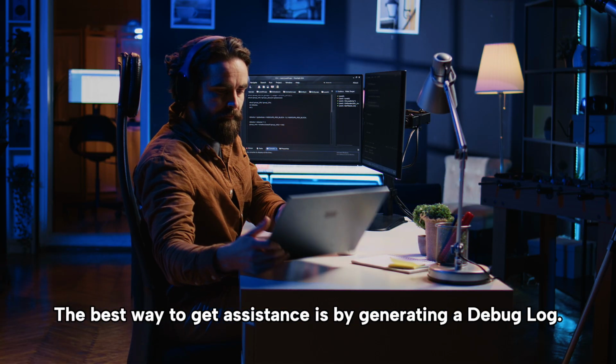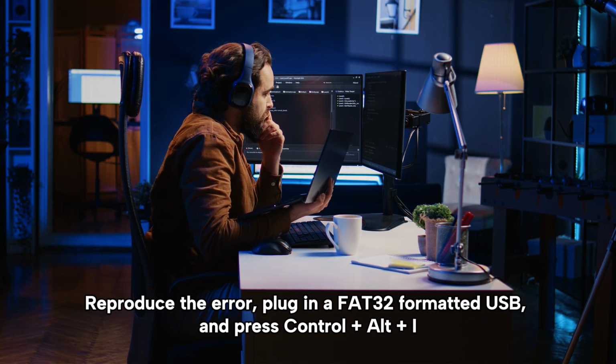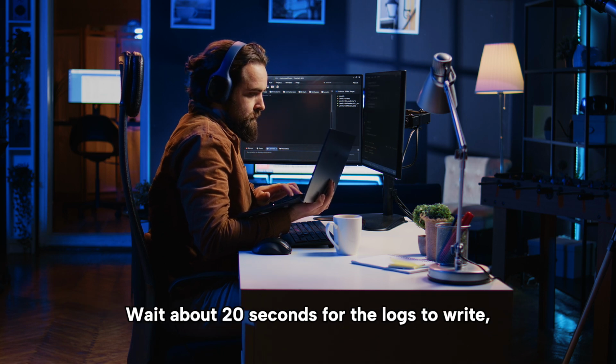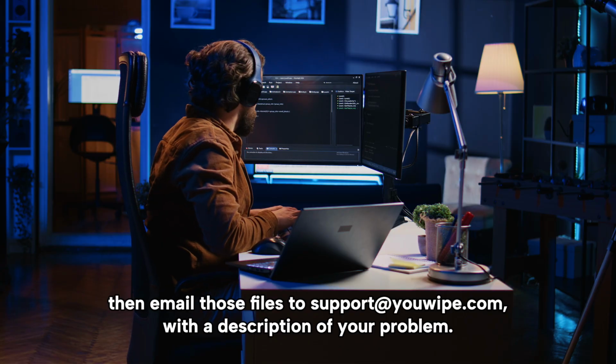The best way to get assistance is by generating a debug log. Reproduce the error, plug in a FAT32 formatted USB, and press Ctrl plus Alt plus I. Wait about 20 seconds for the logs to write, then email those files to support@youwipe.com with a description of your problem.